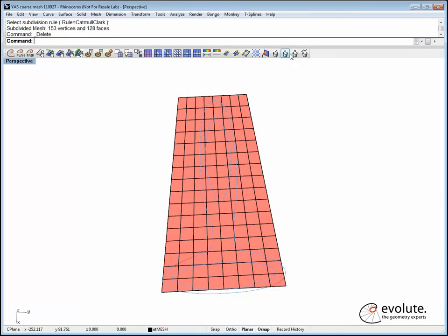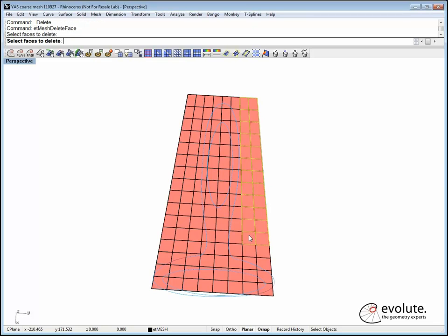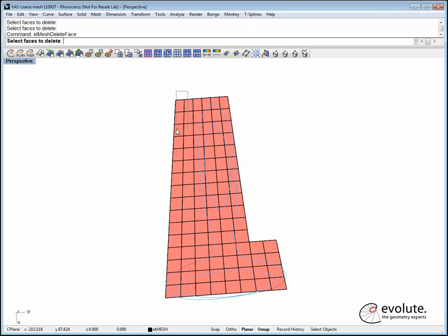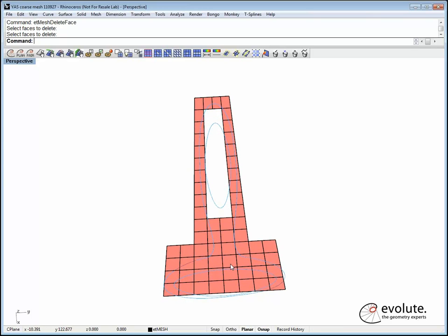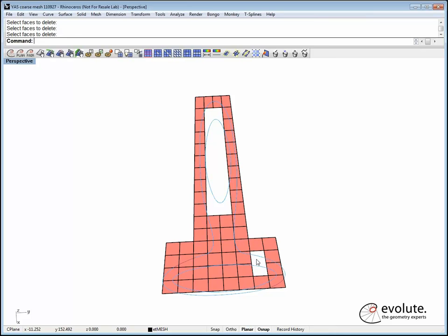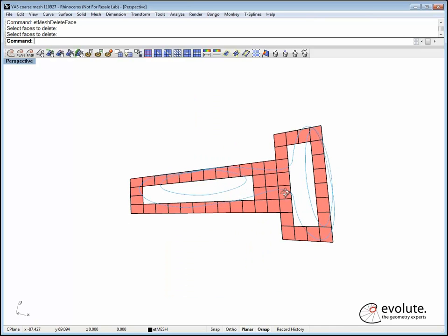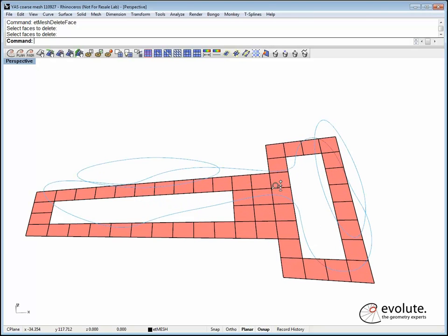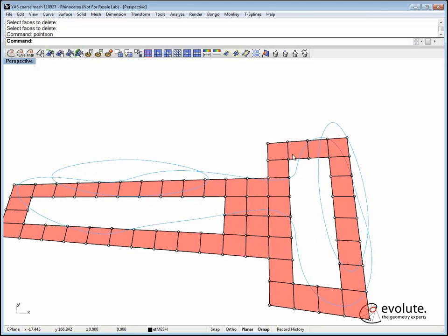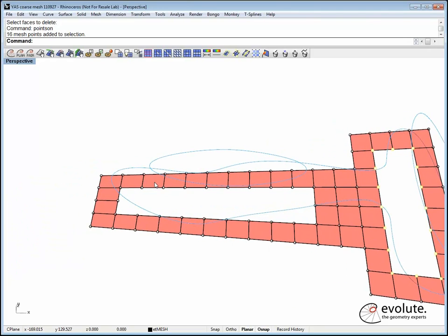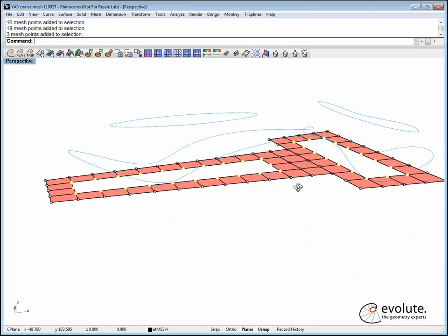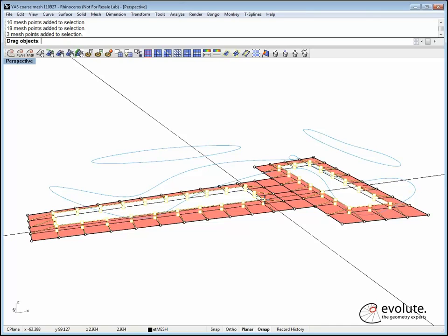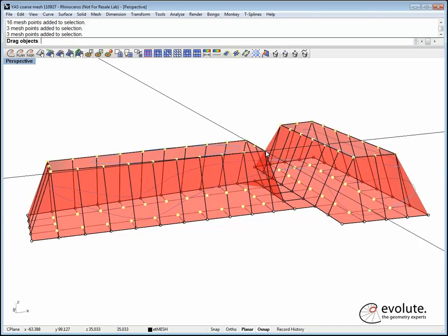I deleted the parent, and again I will edit the mesh, and I will delete a bunch of faces. So I will really want to manipulate this mesh into having a certain appearance I am after. So okay, let's delete a bunch more. Nice and quick. And yep, this is the coarse mesh evolving. So I will turn the grips on, select this bunch of vertices, and select this bunch of vertices, and I'll just move them. I'll just translate them on the Z. Okay, pretty tall, that's good.